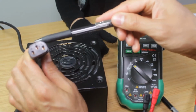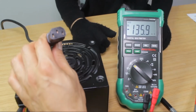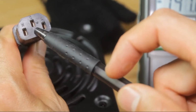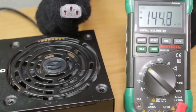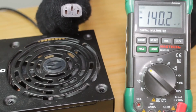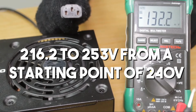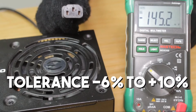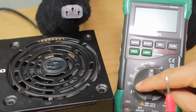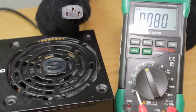We're going to first test the plug to make sure the correct voltage is coming in through from the mains. Here we've got 3 pins, which is neutral, earth and live. We're going to test neutral and live. In UK, the average voltage range between 216.2 to 253 volt, but the average is about 230 or 240, and it will vary during the day. There's a tolerance of -6% to +10%. On your digital multimeter, turn the dial to the AC voltage, which is V with a squiggly line on this model.